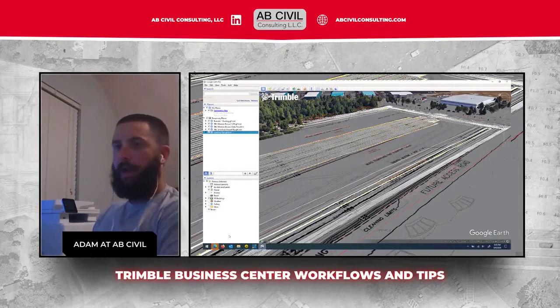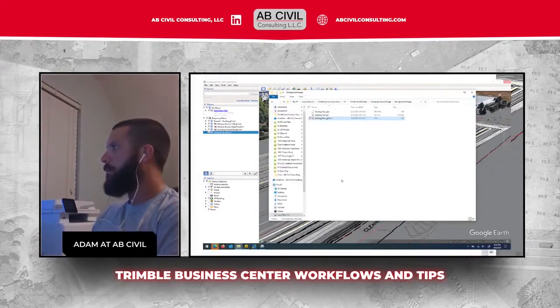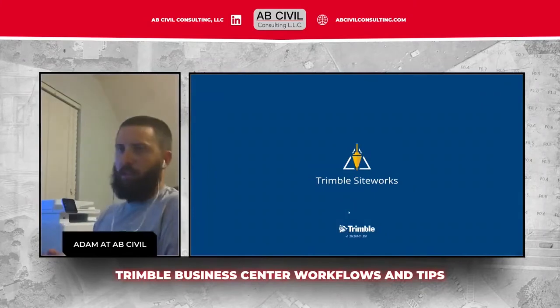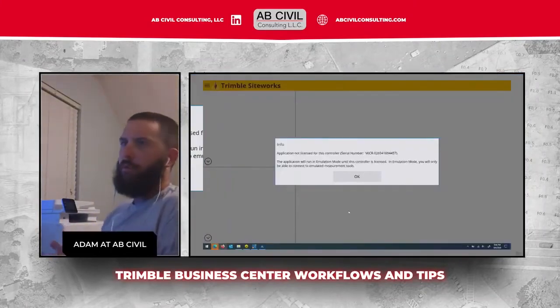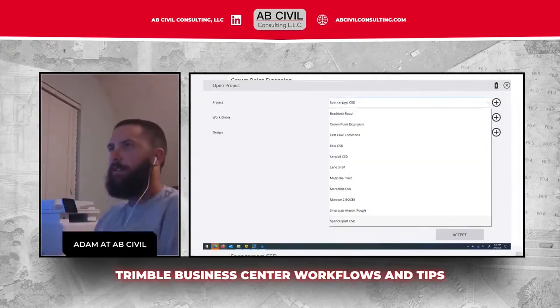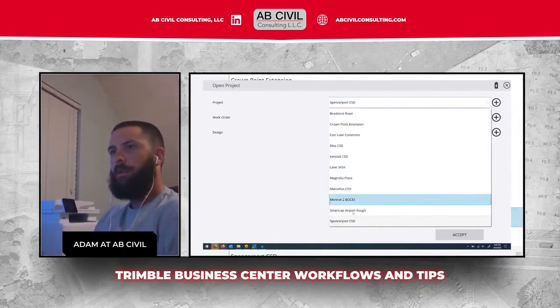See, it wouldn't work before, but I got it to work this time in Business Center, the export of that background image. So I can go back to SiteWorks if I want, back to my emulator to look at this job at least. Yeah, start with your WGS84 closest coordinate system. You can always look up each state on a map and see roughly where it's at. Use that coordinate system. If it doesn't work, try 1927.